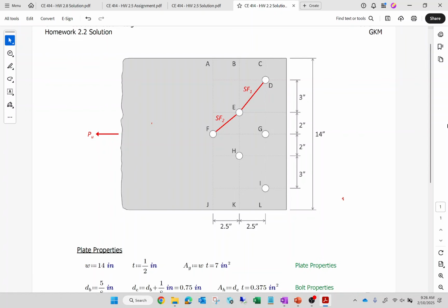Because think, if I take a pair of scissors and I cut through, let's say, a paper plate, these 2 bolts are still holding it down. I'd have to shear through those bolts to separate the member. And my point is, I'm evaluating the strength of the member, not the strength of the member and the bolts. I'm going to look at the bolts later.